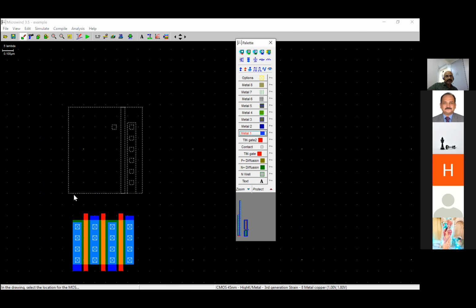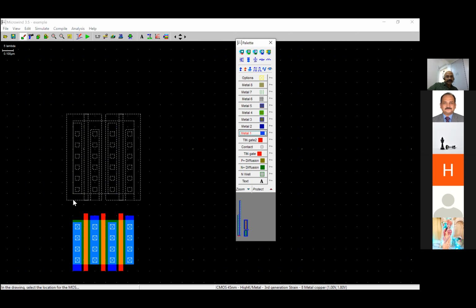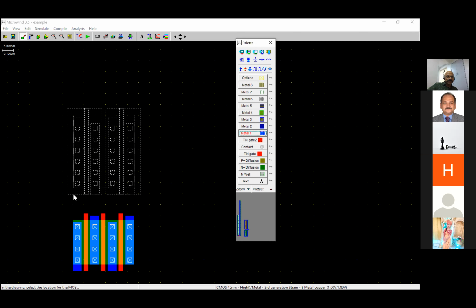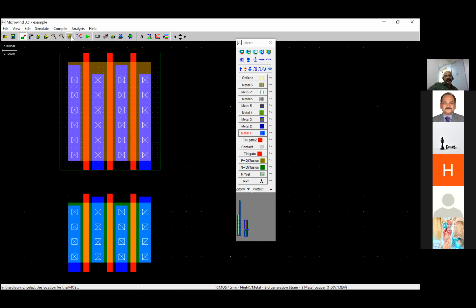You click generate device and you will see that it shows a shadow ghost kind of effect, and keeping a good space between both transistors, you try to align the gate rectangles and left click. Just keep on increasing till you get the matching value with this. Generally, it is like twice, 1.8 times of the NMOS value. Then you can click zoom all and you should see both PMOS. Even though you're not getting the same values there, no problem.